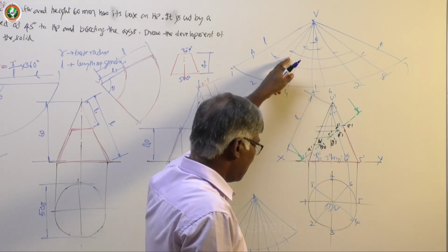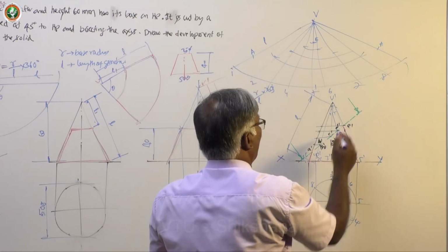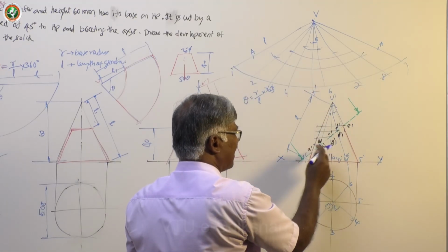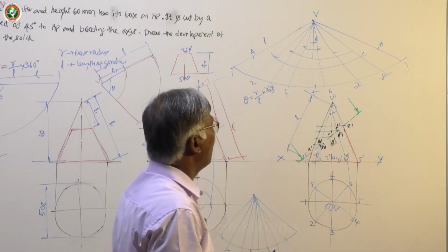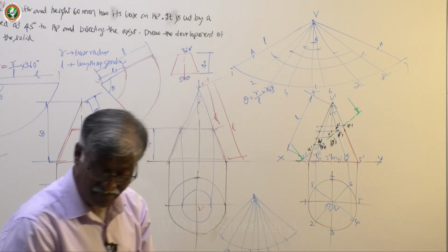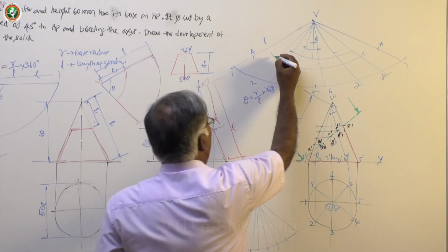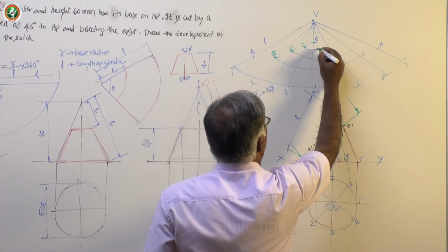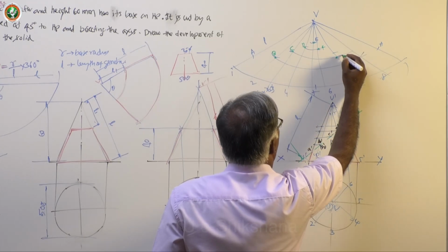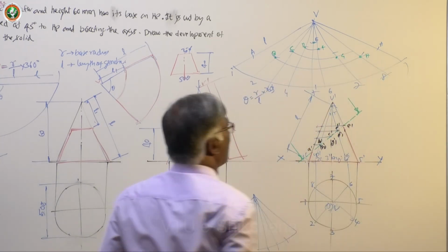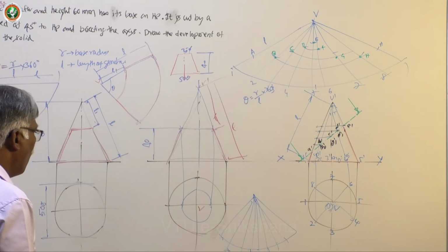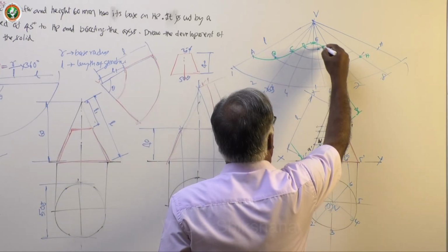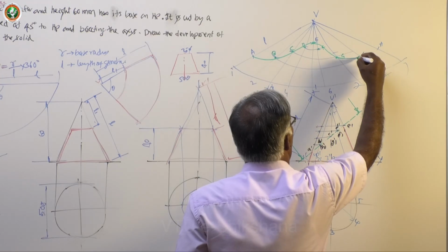Again next point 3 and 7. Draw one more arc by taking this 3 and 7. You can mark here E1 dash, D1 dash, etc. Or you can take in sequence and draw arc. Now this is point B, this is C, this one is D, this is E, this is F, G, H. Now you will get this pattern till A.